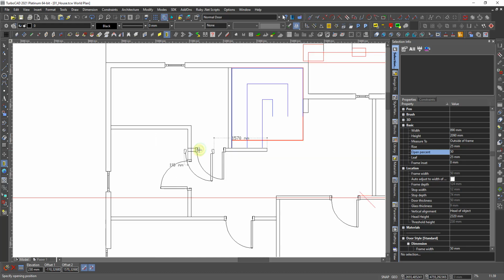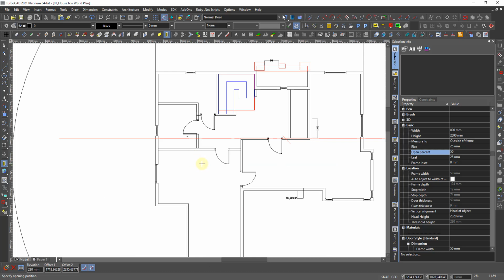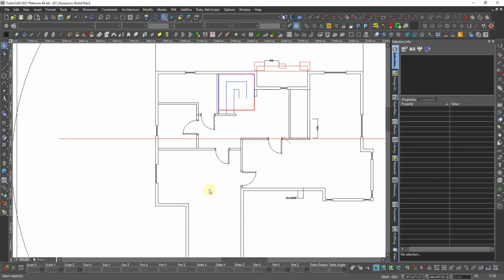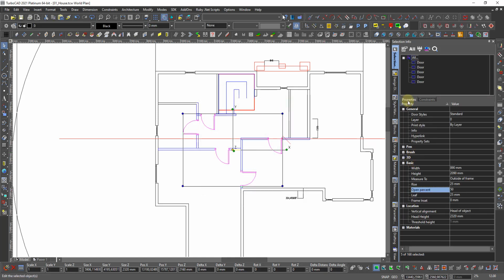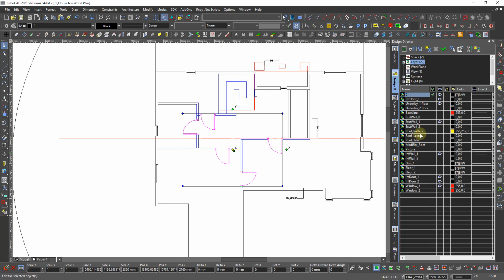There. Then we put the interior door. All the doors weren't put on the correct layer, but that's okay. We finished with all the interior doors. Then I use Control T. Just click in here and then I press D for door. This one and OK. And I go there and I say all of them should be in interior door 1.